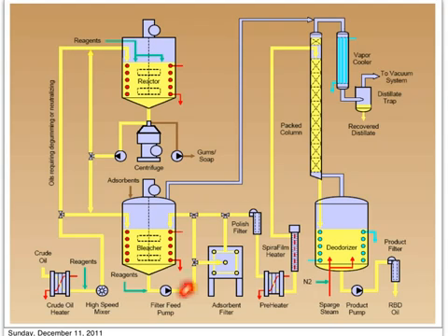After the bleaching, the oil will be pumped through a series of filters to separate the oil from the adsorbent material, and perhaps some polishing step to ensure the spent bleaching earth particles are removed completely. Because the next step is deodorization, before the oil goes through the deodorization process, it's very important to make sure the oil doesn't contain any residual bleaching earth or soap from the previous step.